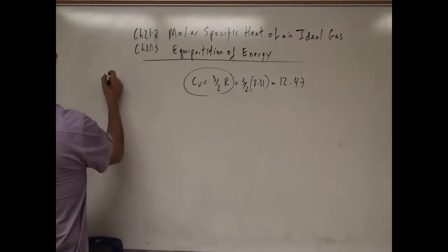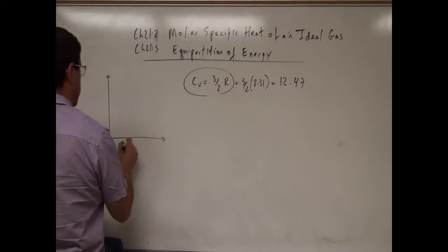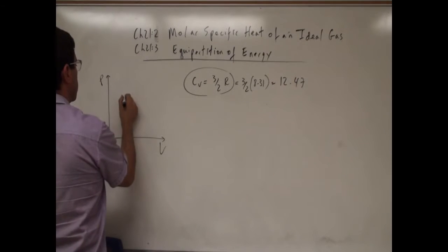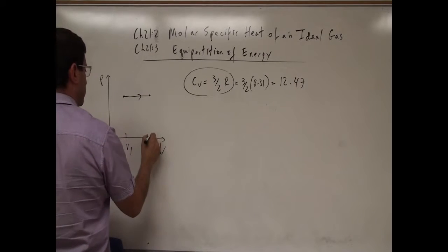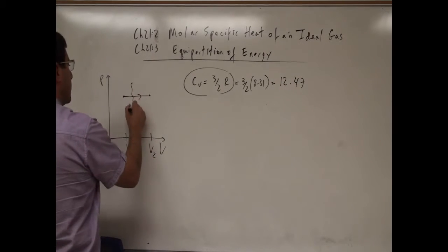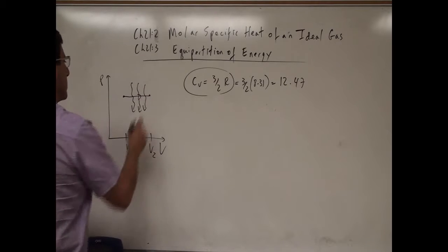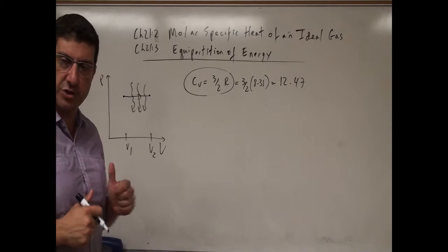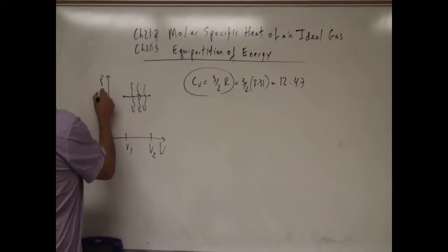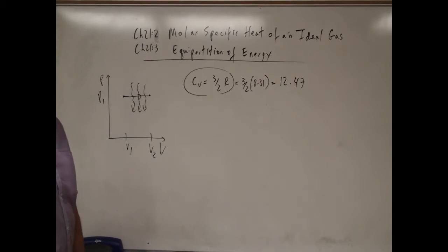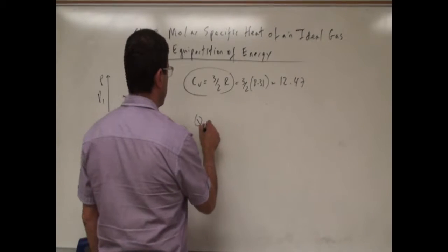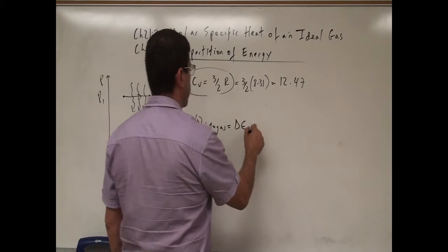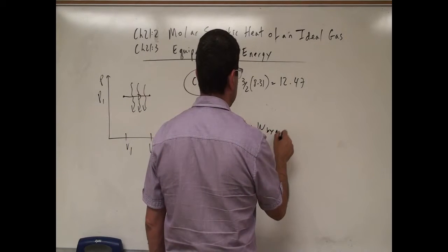So we have the pressure, constant pressure will look something like this, right? PV, then it will start here at V1, and then the pressure will be constant. So if we pour in heat into the gas, right, the gas will expand. We can keep it an isobaric process, right? Keep the pressure constant. So the pressure can stay at a certain P1, right? So what's that going to equal? Q into gas is equal to change in internal energy of gas plus the work done by the gas.